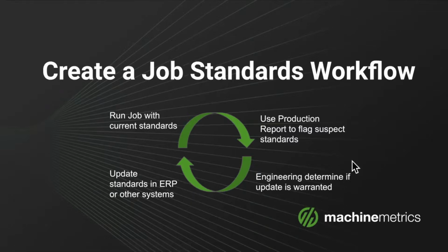And I want to just really quickly touch on this one, engineering determining if an update is warranted. I put engineering because that's typically where we see standards being maintained, although that may look different for your organization. So if it's a different department or a different title, just plug in the one that's appropriate for you. But the point is that you could just pass through updates blindly, but a lot of the time, the run and what happened during the run actually determines whether the cycle time really needs to be updated. And also, most shops put some buffer time into their cycle times, and you don't want to necessarily erode all of your buffer either. So engineering or whatever department really serves as that gatekeeper, so that the data is flagging that there's an issue, but someone is still looking into it to determine whether it should really get updated, as opposed to us just pushing updates.